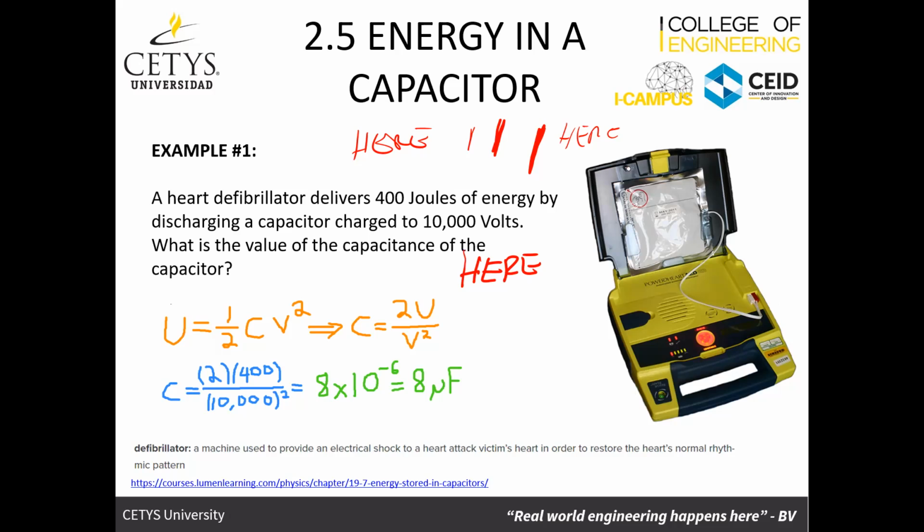Components like capacitors and resistors have certain specific values. So you might find 1 microfarad capacitors or 10 microfarad capacitors, but you might not find an 8 microfarad capacitor. So how could we build an 8 microfarad capacitor using other capacitors in an array of series and parallel? It doesn't necessarily mean that inside this device there's 1 capacitor. There might be many capacitors, and the equivalent capacitance is this value that we have here.